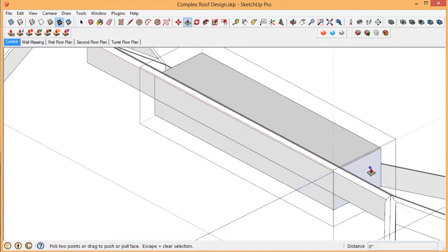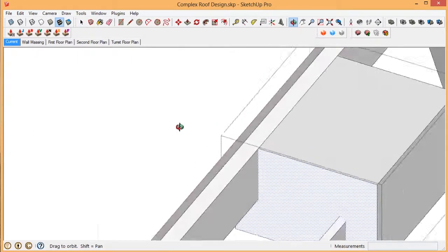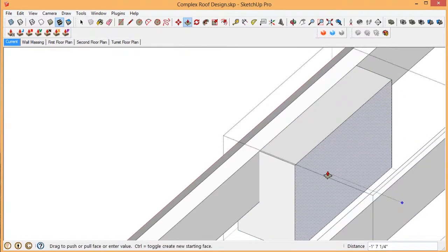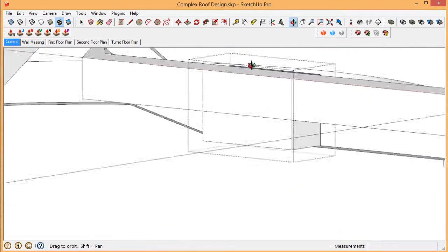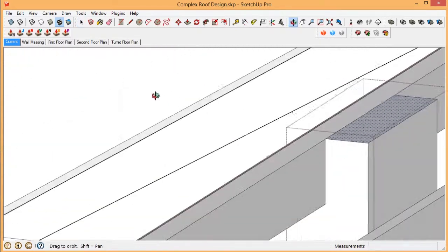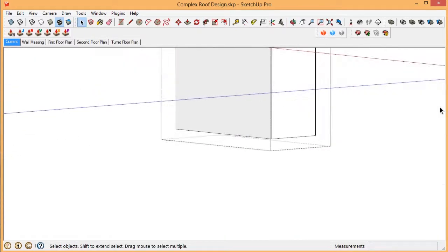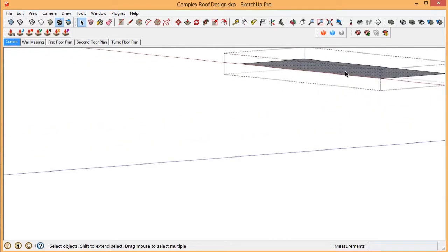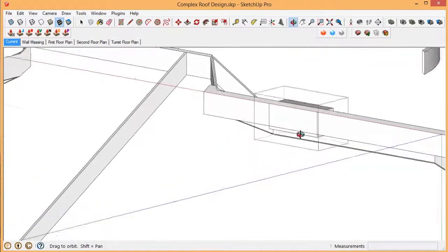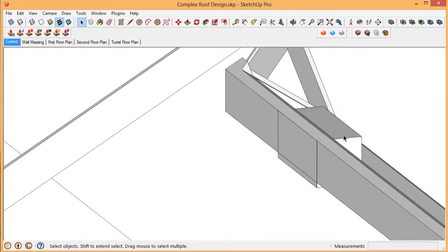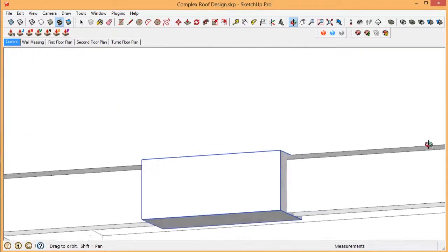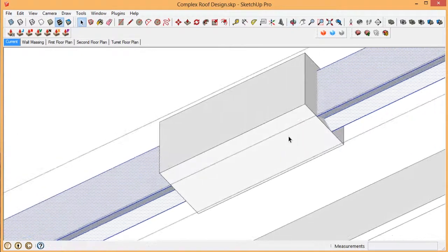This rectangle is too big, so I'm going to go ahead and make it smaller, a little more convenient. And I'm going to change the height of it to be the height of the finished ridge, in this case 15 inches. In fact, I'm just going to delete the bottom and extrude this 15 inches down. It's a little easier. Then we'll use the circle tool, our favorite circle tool, cut method, to trim the bottom off the ridge.